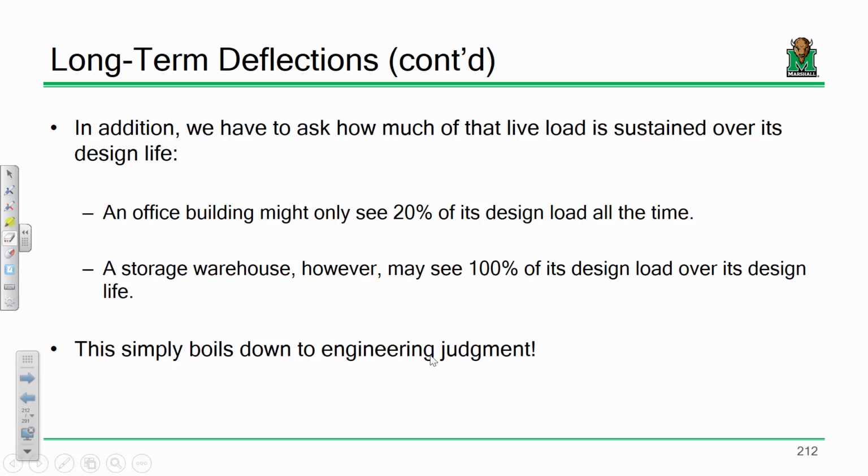But in all seriousness, it's fair to say that in a storage facility type situation, it's a safe assumption that most of that load is always going to be there. That probably isn't a reasonable assumption for this classroom, okay? Because think about this. This classroom is designed for, I think what we said, like 50 pounds per square foot.